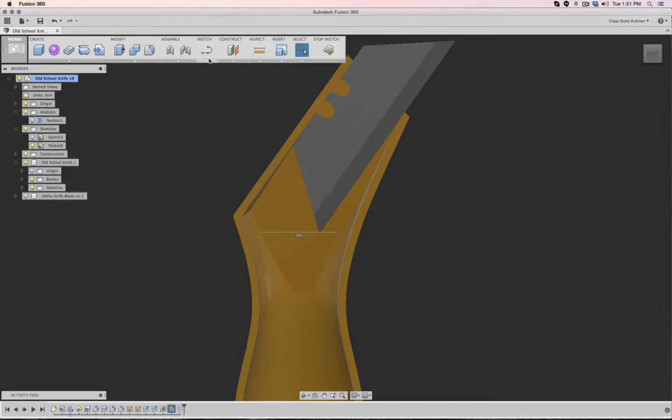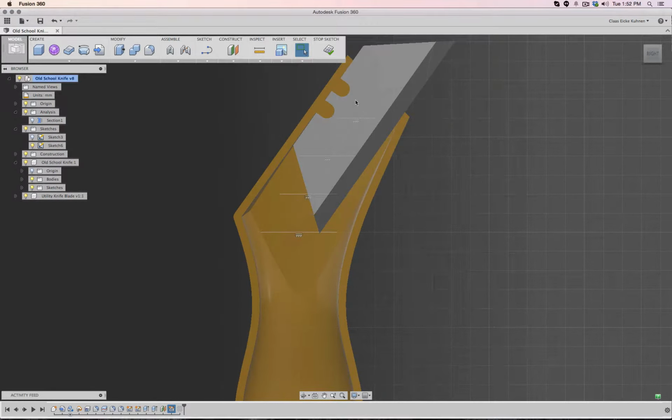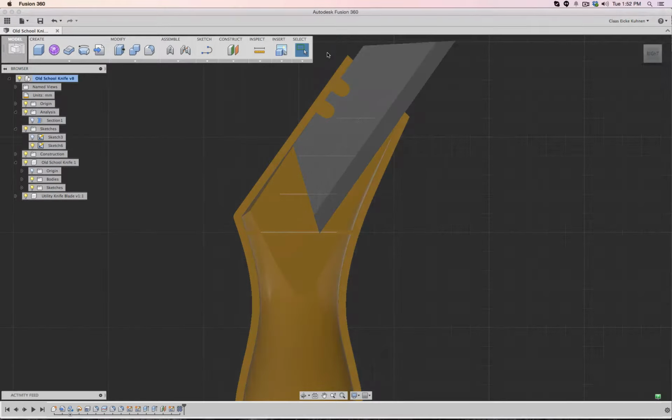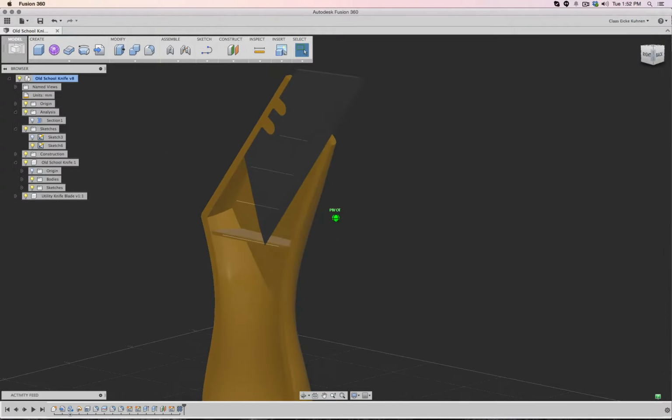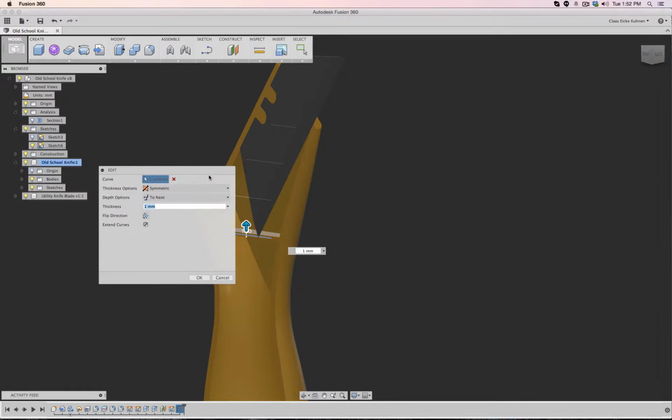So maybe for this web, actually I would like to create more lines. So I go to edit, and here I'm going to simply use the grid to make strategic positions. I make these lines every second grid point, and hopefully this should be enough. Let's see. Stop sketch. And obviously I have to update which edges I would like to select.